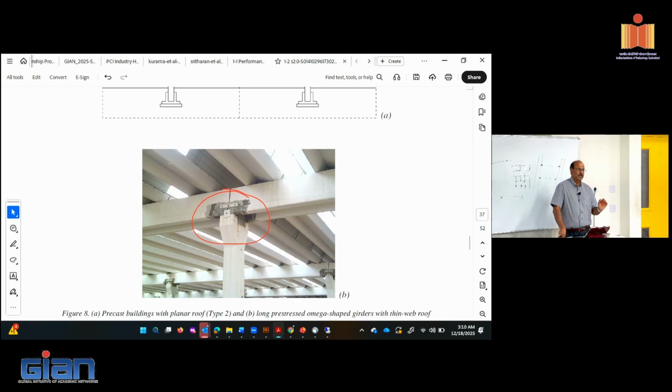So if you go back to this concept here, I said the concept is strong column, weak beam, meaning that the hinges are going to develop in the beam. Now transport that knowledge to a precast system, then the weak beam concept basically says the connection has to be weaker, right?